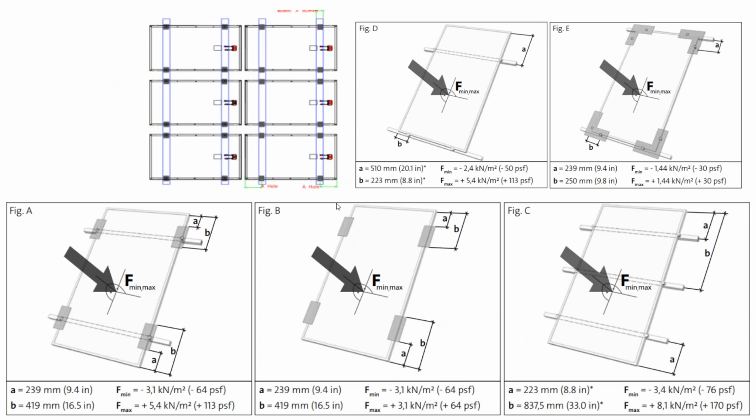And so as an engineer, I love this stuff, looking up a solar array and looking at mounting clip zones and seeing how I have different wind ratings and different load ratings based on how I choose to attach the panel to a particular racking system. There are even configurations for the same panel and the same racking system, but with stronger loads by putting additional reinforcement on. And so, if planning for a hurricane zone, it might not be a matter of buying a different solar panel, but instead just buying some more racking and adding some more reinforcement to it.